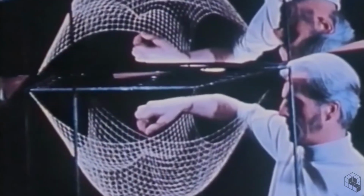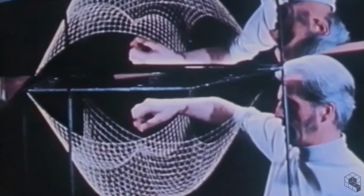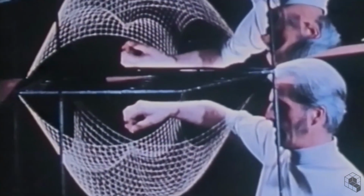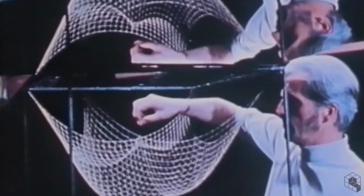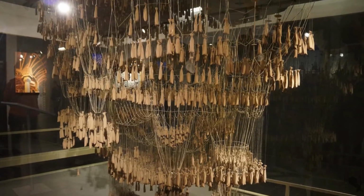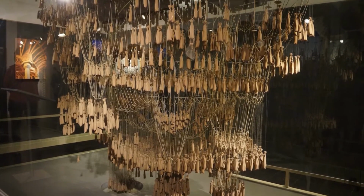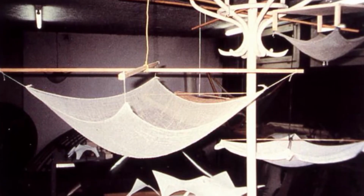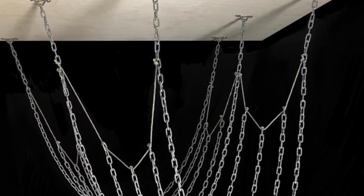The oldest documented method of physical form finding is the reverse hanging model, used for designing arches, vaults, and shells. It is a physical model with an elastic cable or membrane with no rotational stiffness, subjected to gravity forces, in order to obtain a structural state of pure tension. This form is called funicular, which, when inverted, identifies a compression-only version of itself.